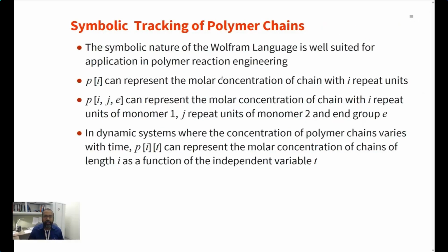The symbolic nature of the Wolfram language is definitely well suited for application in polymer reaction engineering, and it offers considerable flexibility. For example, P of I can represent the molar concentration of chains with I repeat units, and this makes it possible to use functions like Table to quickly generate symbolic representations for all species in the reactors.